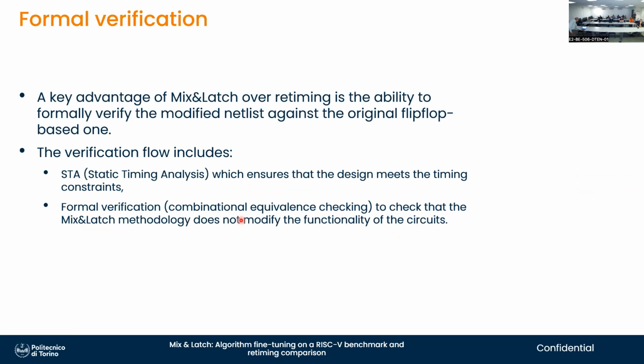So with respect to formal verification, we use standard static timing analysis tools to check the delays. They support all kinds of flip-flops and latches. They are actually the only tool in the chain that supports that very well, because people can do these designs by hand. They don't know how to do it, most likely, but they can in principle, and so the tools support that.